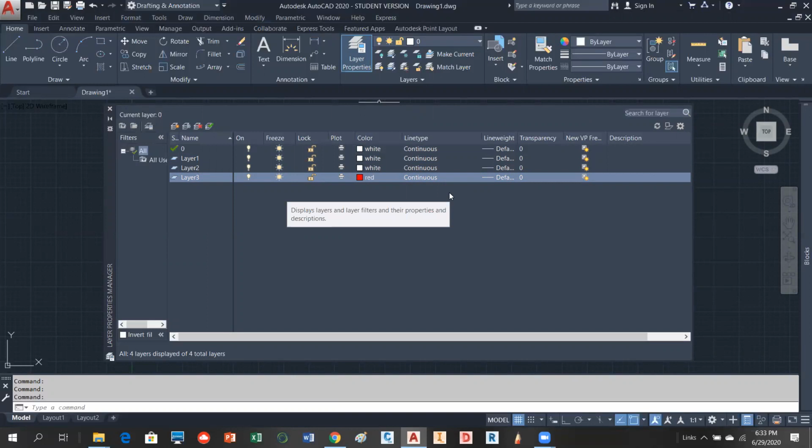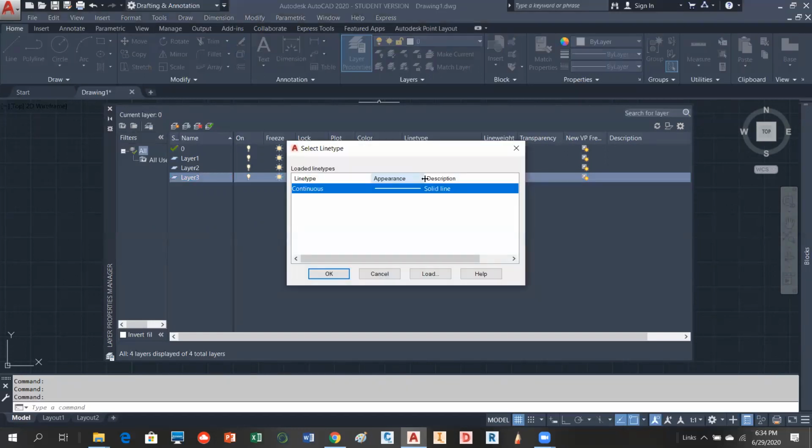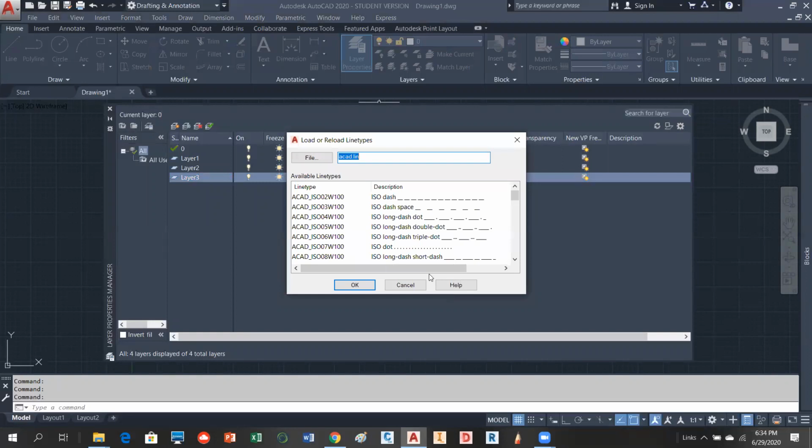Okay, what we're going to have to do is load the line types into the drawing. So here's the easiest way to do this. We talked about this last week. If you hadn't had a chance to do that assignment 4, you haven't had a chance to do this yet. So you're going to go to any of those line types and click it. Then you right click or go to load. And the easiest thing to do is just load every line type into your drawing.